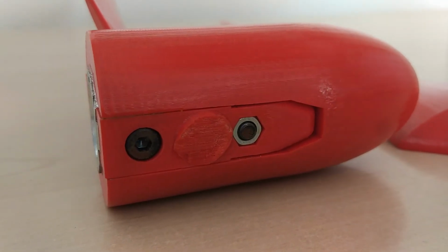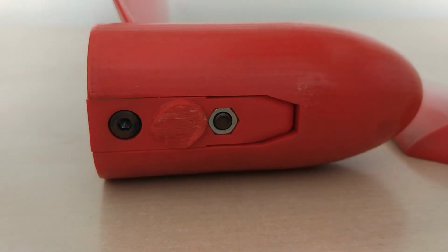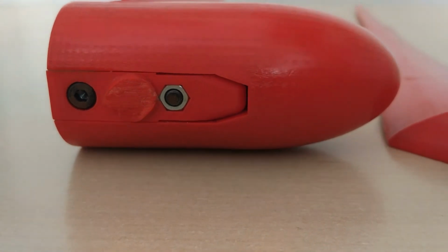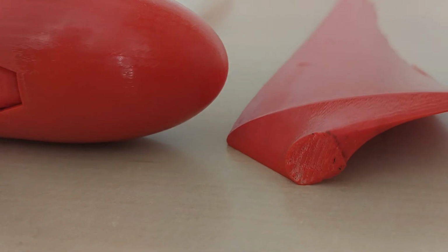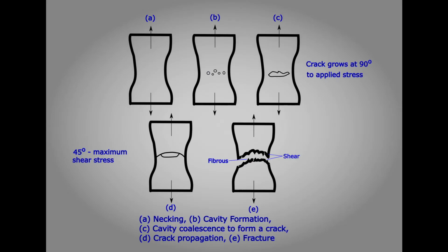The way our turbine failed remains interesting, and shows the complexity of this entire challenge. The broken root shows that the failure mode is mixed, and that fatigue caused by vibrations played an important role. As a result, it would have been very difficult to predict. However, it is also possible that taking larger safety factors could have prevented such an early failure.